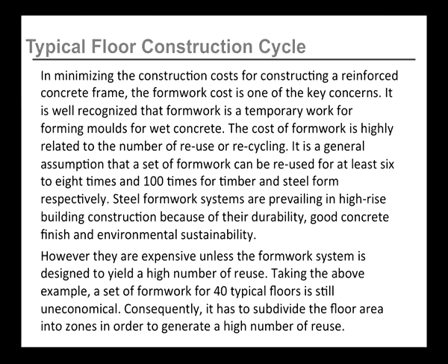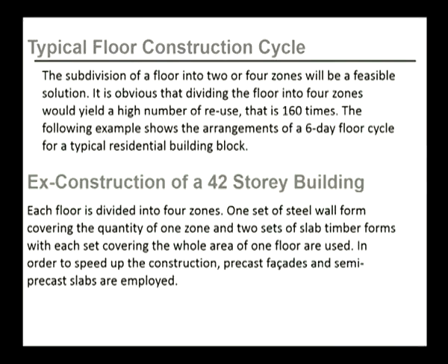Consequently, the floor area has to be subdivided into zones in order to generate a high number of reuses. The subdivision of a floor into 2 or 4 zones will be a feasible solution. It is obvious that dividing the floor into 4 zones would yield a high number of reuses, approximately 160 times, if we consider the example that we talked about earlier.